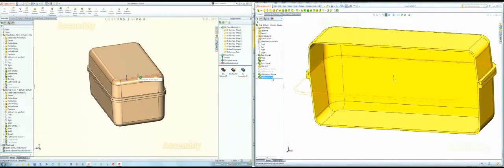So that's one thing we're not going to try to do on the multi-body side. We're not going to try to separate everything out, because when you get to the lip and groove, you're going to have really bad luck trying to separate it out or delete one and not the other. So it's kind of equivalent to the assembly. You've got two features here. Over there you've got two features, but they happen to be spread out over two parts and tied together through the assembly file.